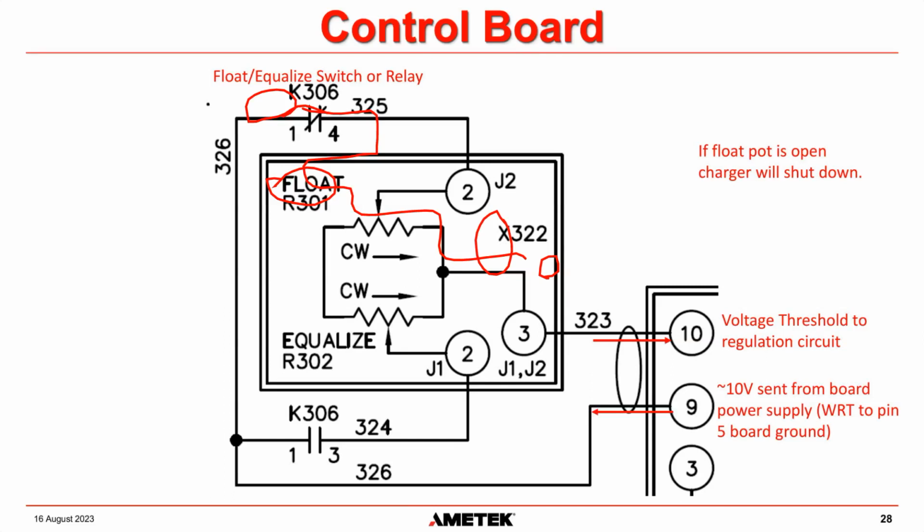So the default fail-safe position is if we have an open in our voltage threshold circuit, then we're going to get 0 volts out of the charger. So it's very important that the regulation circuit works.